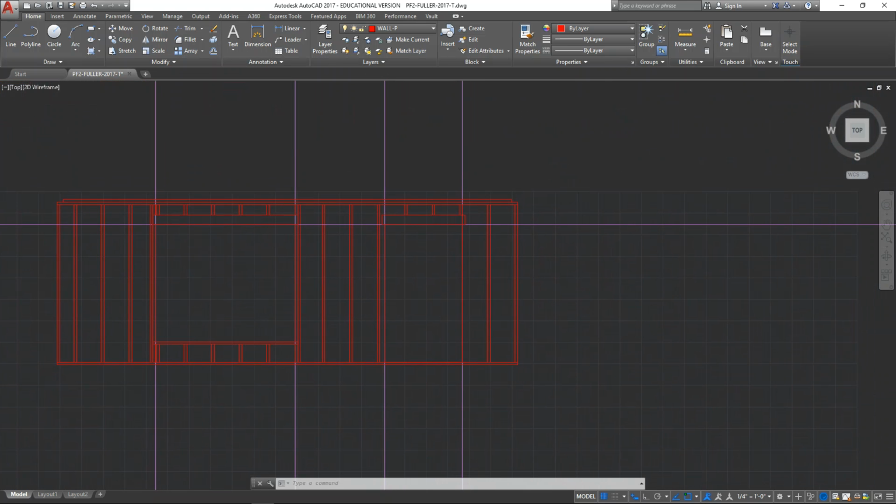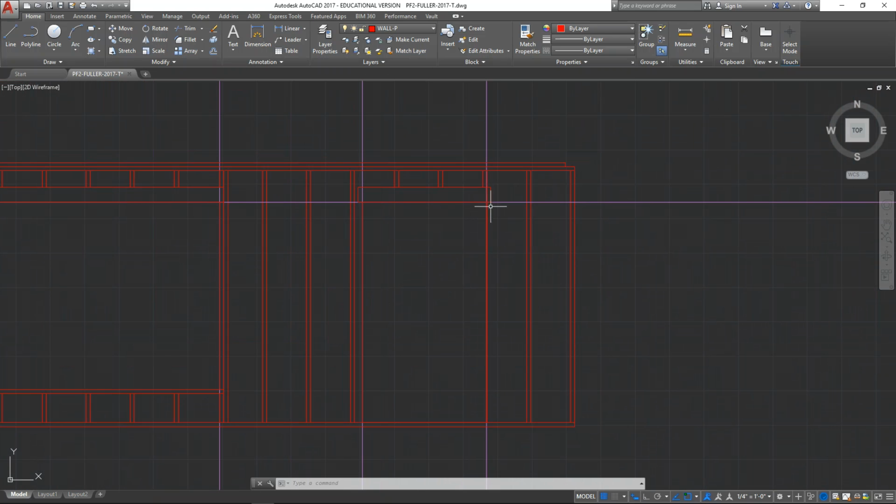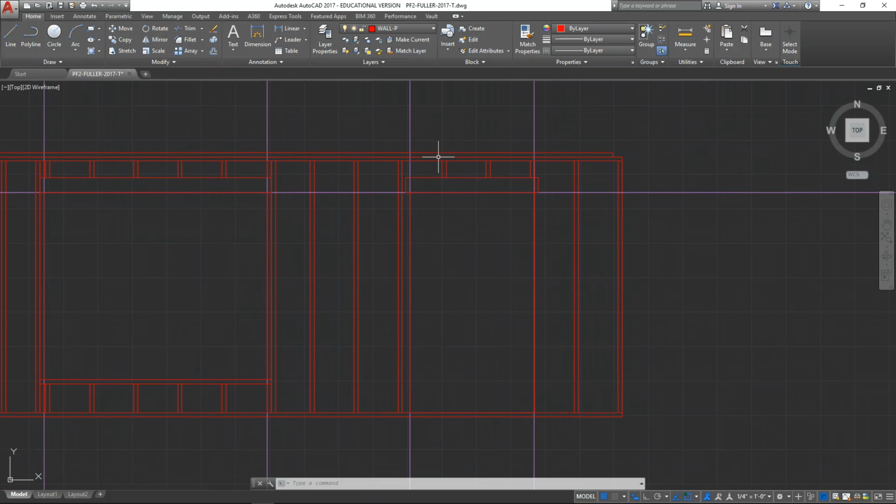But I do have to do some further trimming. I do have to put trimmers on either side of that header. And the ground basically is what's going to be supporting that instead of the sill. And let's see, we're going to just copy this line. Okay, we're going to offset that line. We're going to offset 1-1/2 inches. Over there, then over there.